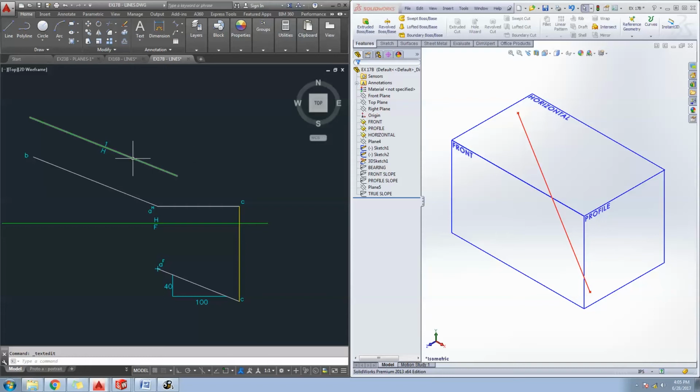Now, because this folding line is parallel with this line right here, I'm guaranteed that whatever view I get out here is guaranteed to be in true length. But I don't have any points over here to pick up or offset. Well, it's not entirely true. I have 1 point, and that's actually the point that we're going to have to work with. So here's what we do.